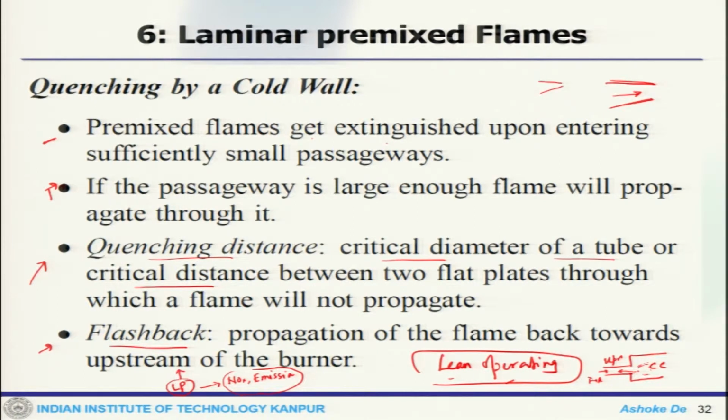So that means, again, as we slowly get deeper and deeper into the discussions, you can see how things are connected, which we started up in the introduction showing some pictures of what could happen or what could not. But here you see that the whole issue is an optimization problem with multifaceted issues; it is not a single dimensional problem. You need to operate at lean condition, but then lean condition also not only causes flashback, it will also lead to a blowout.